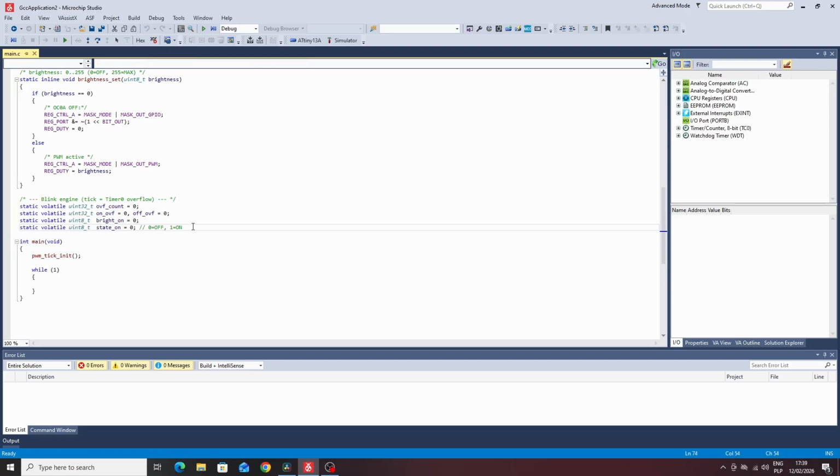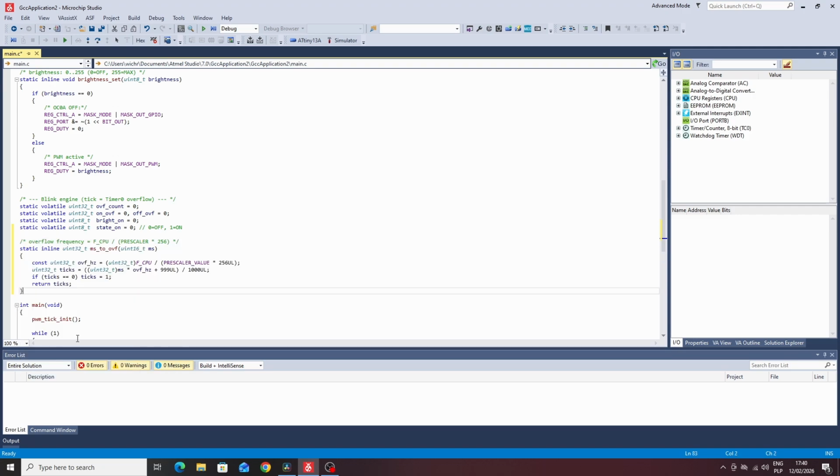If we change the LED state on every timer overflow, the LED will toggle hundreds of times per second. In this case, around 585 times per second, which would look like it's constantly on. That's far too fast for visible blinking. So, instead of reacting to every overflow, we count them. We only change the LED state after a specific number of overflow events have occurred. That allows us to slow the switching down to a human-visible rate.